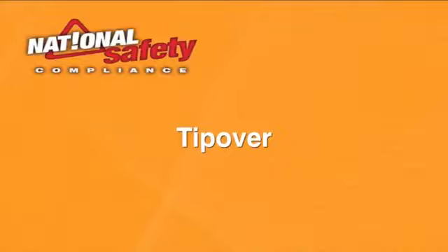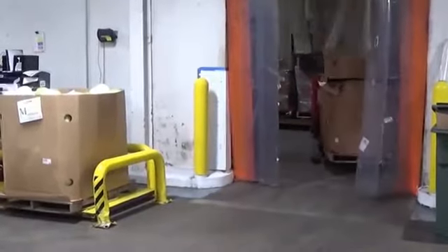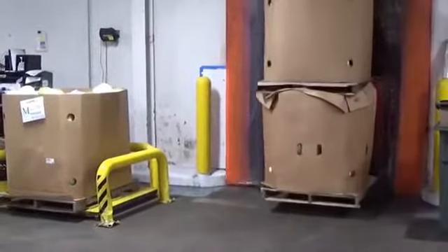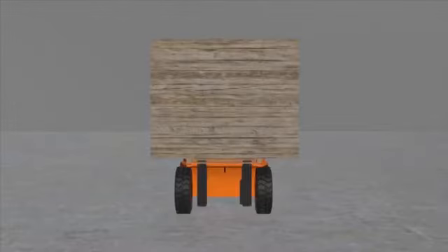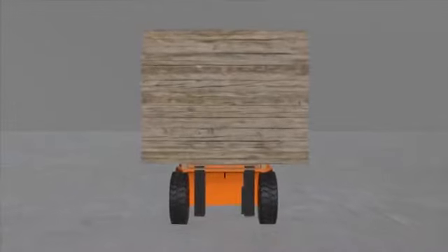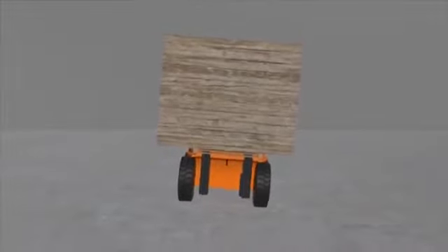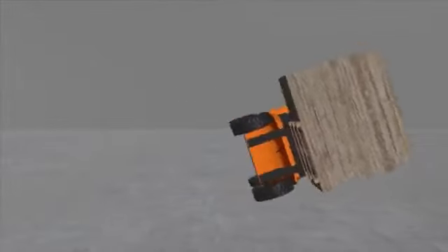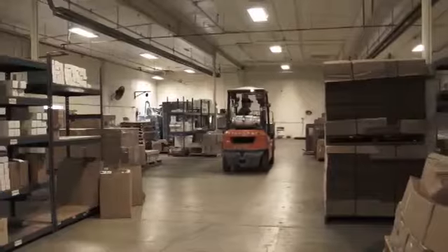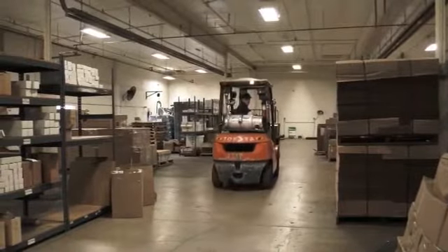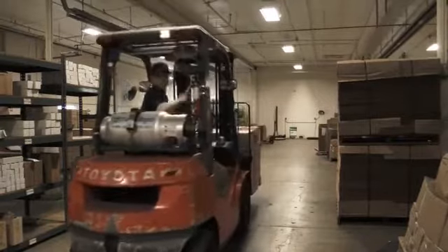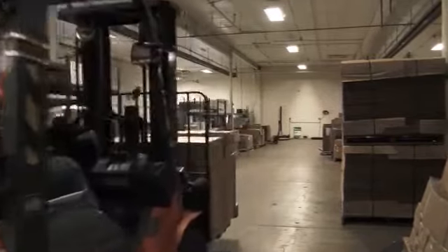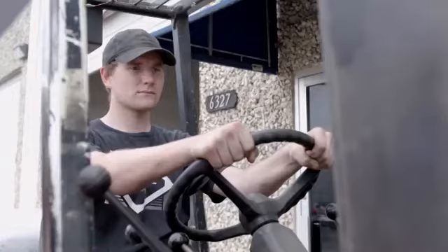Tip over. There are two basic types of tip overs in a forklift: a forward tip, referred to as longitudinal tip, and a lateral or side tip. Forklift tip overs are the leading cause of fatalities involving forklifts. For tip overs on a sit-down counterbalance truck, which are the most common, the following tips may save you from serious injury. Don't jump. Stay in the forklift.